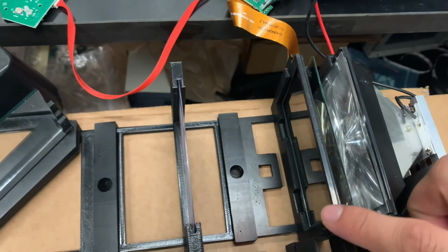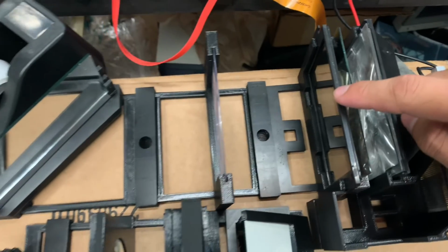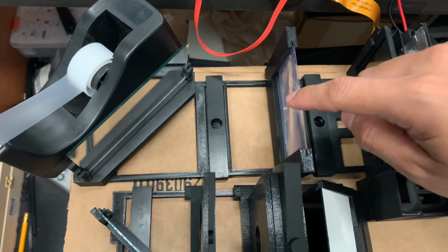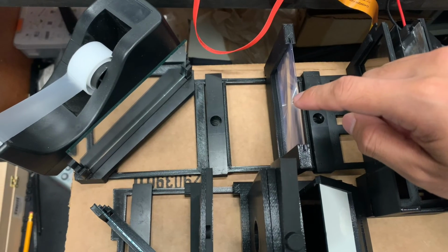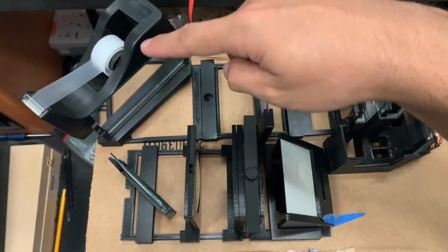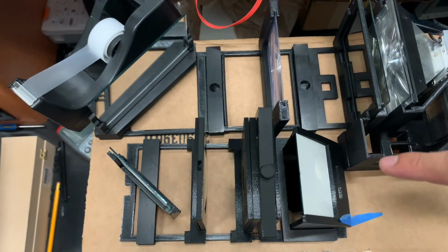A 3.9 inch LCD with a resolution of 800 by 480 will generate a color image. To reduce the light loss in the system, a second Fresnel lens is used to gather the light. To fit the length of our system inside the device, we use two mirrors to steer the optical path length.